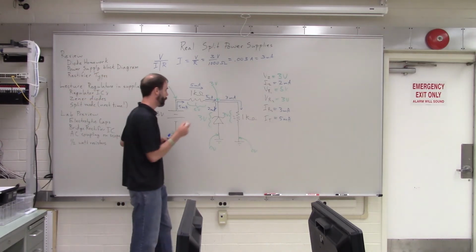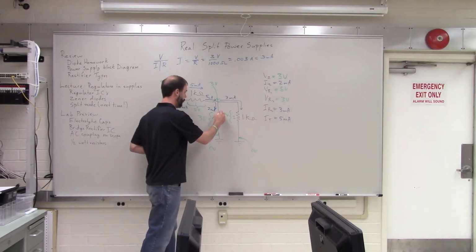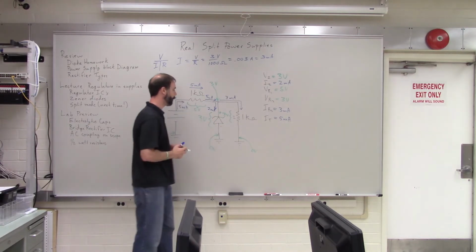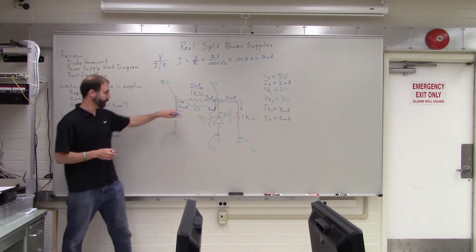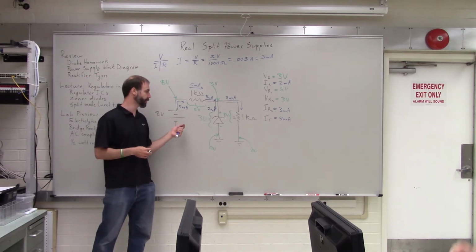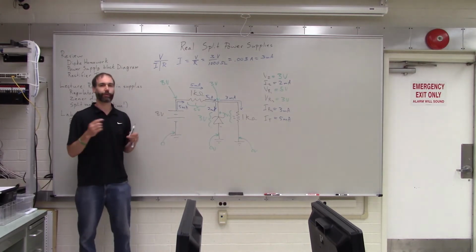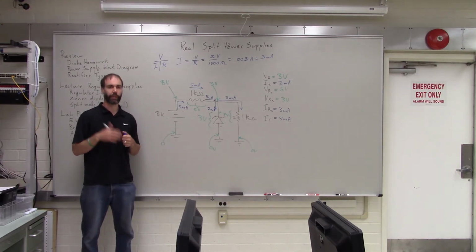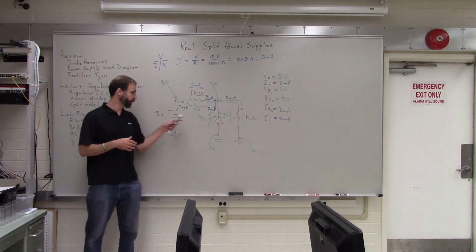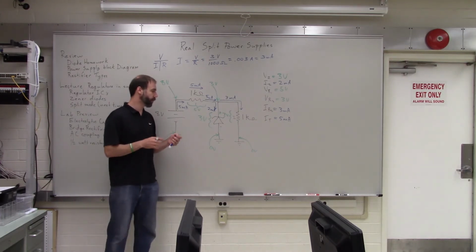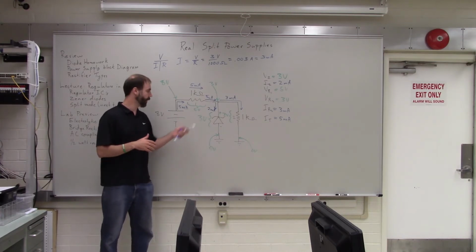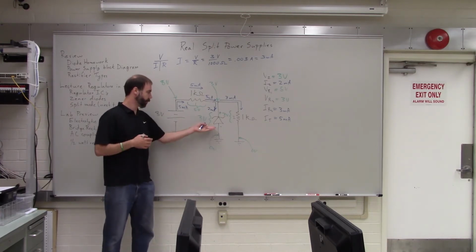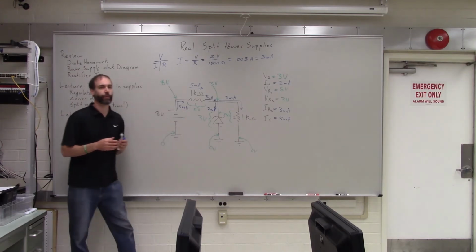Good question. This has a positive voltage there and a negative voltage there, so it is reverse biased. If the Zener diode had been forward biased, how much voltage would you have across it? About 0.7 volts. Zener diodes and regular diodes all have about 0.6 to 0.7 volts across them when they're forward biased. When they're reverse biased, that's when Zener diodes have their specific voltage across them.